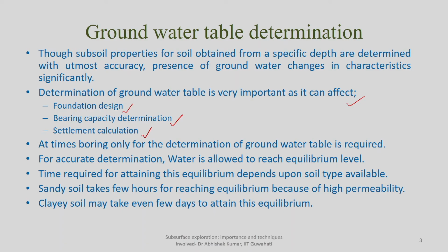At times, as I mentioned in the next point, people do boring only for the determination of groundwater table, which may not be available otherwise. If you have wells in the nearby location, or some lakes, that can possibly give you an indication of the groundwater table level. But if you do not have those kinds of resources in the vicinity of the site, you have to drill a borehole, particularly because you are boring here not for collection of soil samples. So, you can go with boring methods and no sampling will be required. This will give you, on average, the depth of the groundwater table at your site.